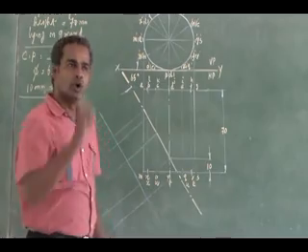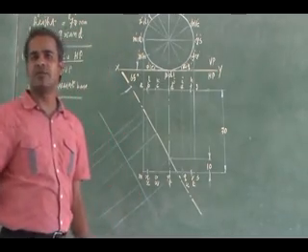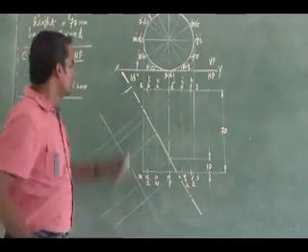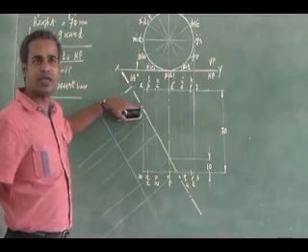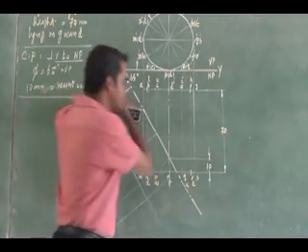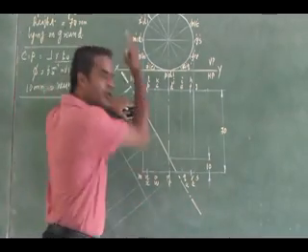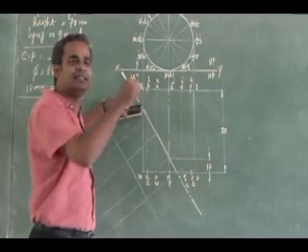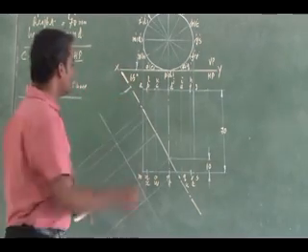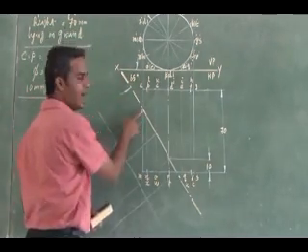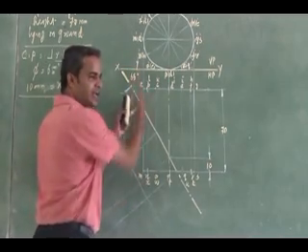Now, notating your cutting points. Listen carefully. Notating your cutting points. You start from the left extreme, searching for the visible generators it cuts. Then you come back in the same manner, searching for the hidden generators it cuts. So here you see, at the extreme I will have only one generator.